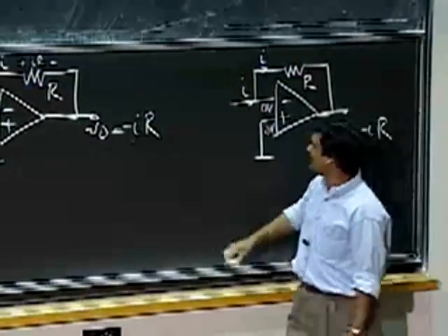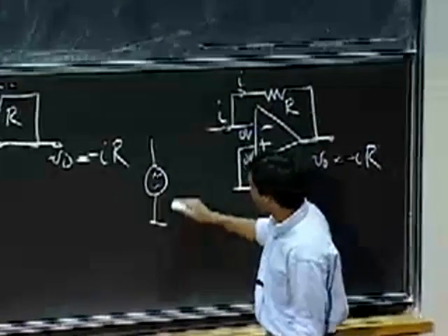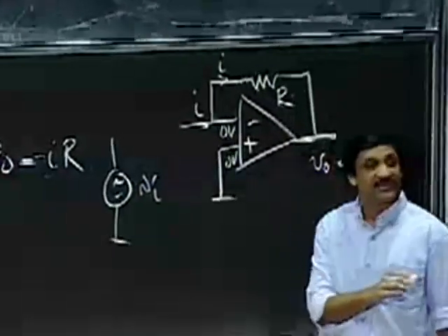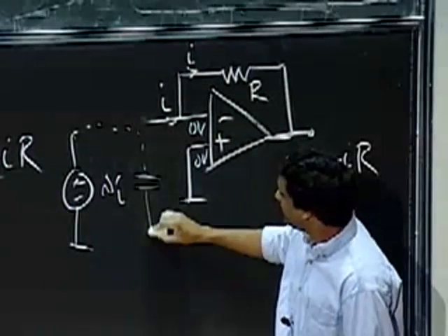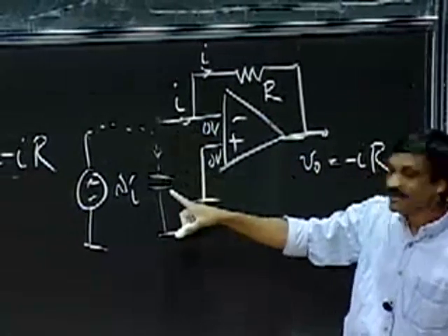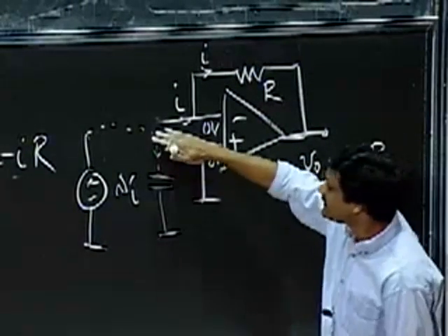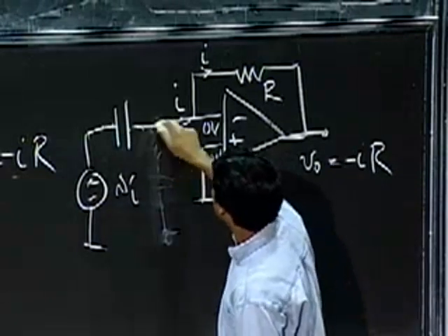So the poor little capacitor doesn't know the difference. I have really suckered the little beast. So this is VI. Remember this: my I through the capacitor is proportional to C dV/dt. Instead, what I've done is taken this guy and stuck it here to get something like this.